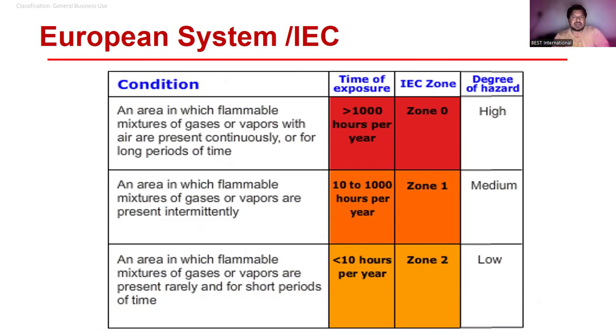Then they make sure the right set of rules, regulations or safety best practices are used for isolation and LOTO: how to close the valve, how to put lock and tag, how to drain out, how to make sure there is no residual or remaining energy. Everything is done. If any fumes are there, how to purge the line using inert gas or nitrogen. In other words, how they make sure oxygen is not coming your way when you are purging with nitrogen. So all these things have plenty of importance, which you need to consider because it's a high risk area, right?